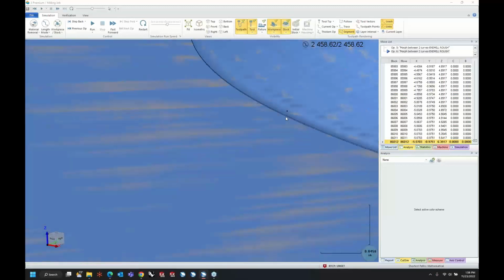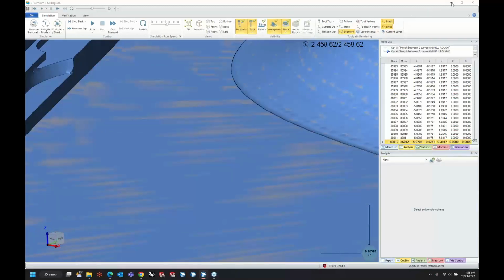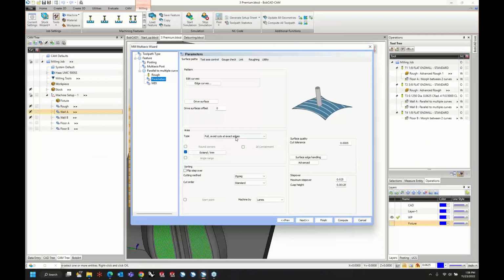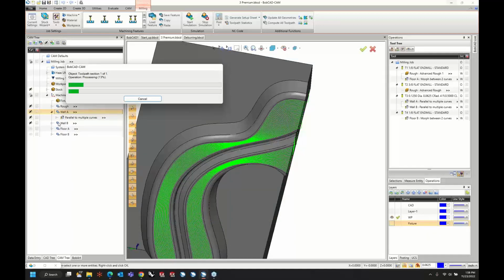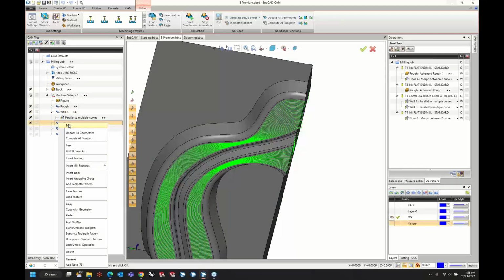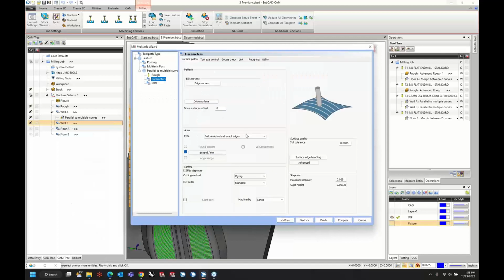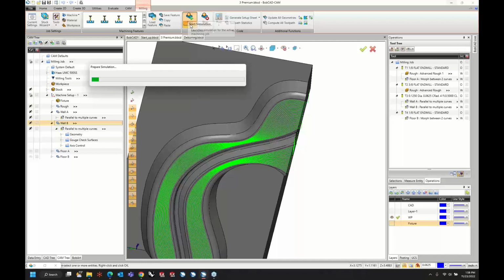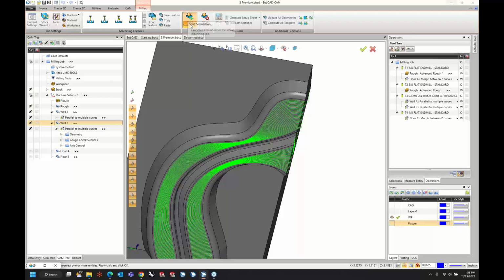I may want to use the ball end mill, or even, let's double check our walls, because this could be a void. Yep, this is void exact edges. So let's do exact surface edges for both of these. And that may change the simulation enough. It may change the quality enough where we won't need to extend it out or anything. If not, I'll switch the other one to a ball.